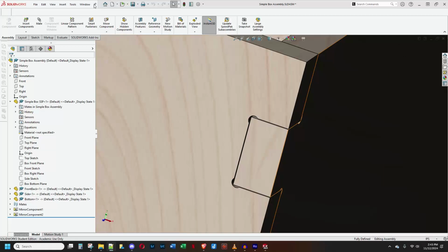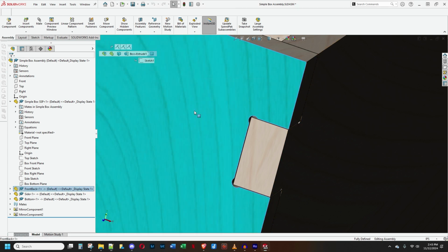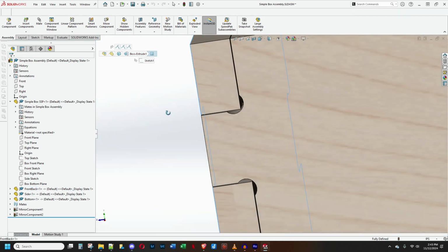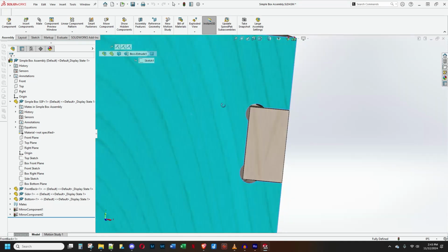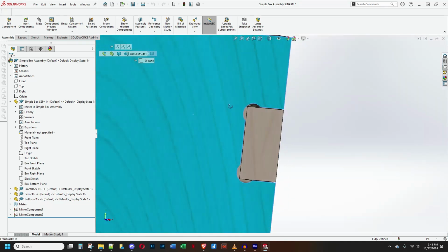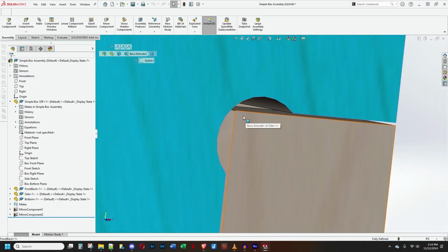When I see CNC woodworking projects like this on the internet, when I'm out shopping around, let's get a 1/4 inch. That's not... yeah, see, that's typically what I see. It's big, ugly dog bones. So I got to thinking, well, what is the minimum that I need to get around that? And it turns out that I could get by with 1/8 of an inch.